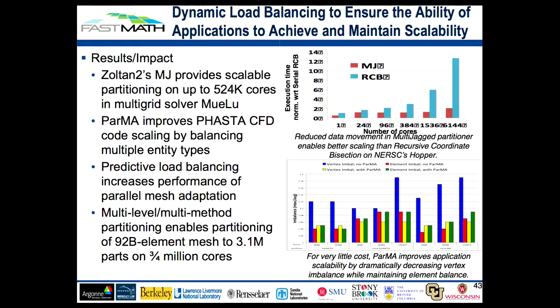Now one would think, well, I'm doing that for load balance. I'm actually doing that for straight survival requirements, because if I don't do that, what I'm going to have is very large imbalances in the amount of memory use on the mesh as it gets much bigger, because of all the refinements in specific areas, and I blow away the memory on a specific node while other nodes are actually using less memory if I don't do predictive load balancing.